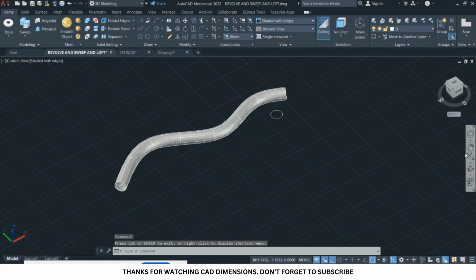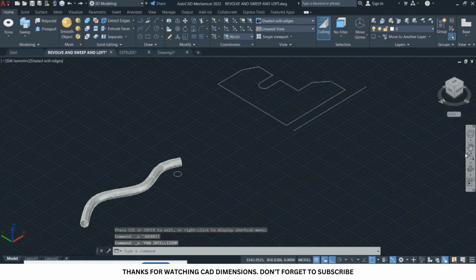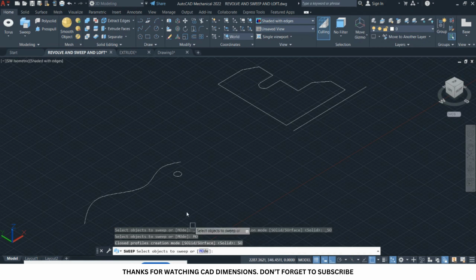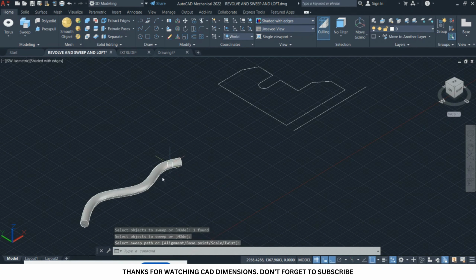So you can sweep so that you can get a hollow, or you can sweep so that you can get a solid. Let's try again. This time round I select mode. If you want solid, you select the solid and select the circle, press enter, then you select the path, then you get it. So that is that.